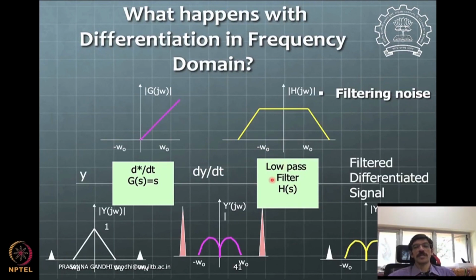Then one can use s equal to this bilinear transform formula and get that as a discrete domain transfer function, and using a discrete domain transfer function you can convert it into the discrete domain time equations. Okay, so how do we do that? That will be done by using this shift operator.